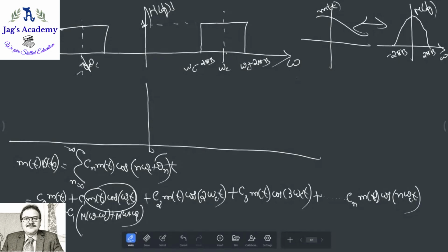Right? Now, can you tell me, how do you draw the spectrum of this M of f? As it is, right? I will just write this as it is, same M of f only. This is 2 pi B, this is minus 2 pi B. Plus this one, right? Now what is this one? Shifting, right? This is shifted by omega c, shifted by minus omega c, yes or no? So same, I will have one here, shifted by omega c here, shifted by minus omega c here.